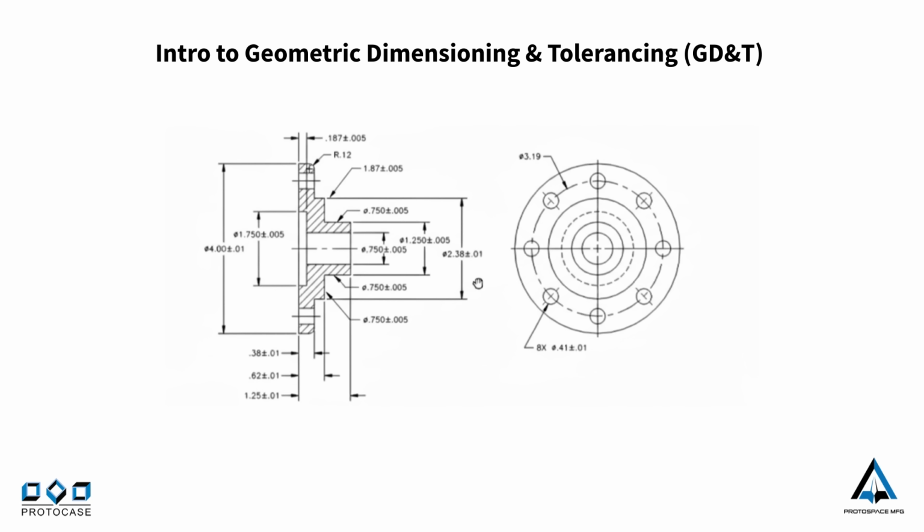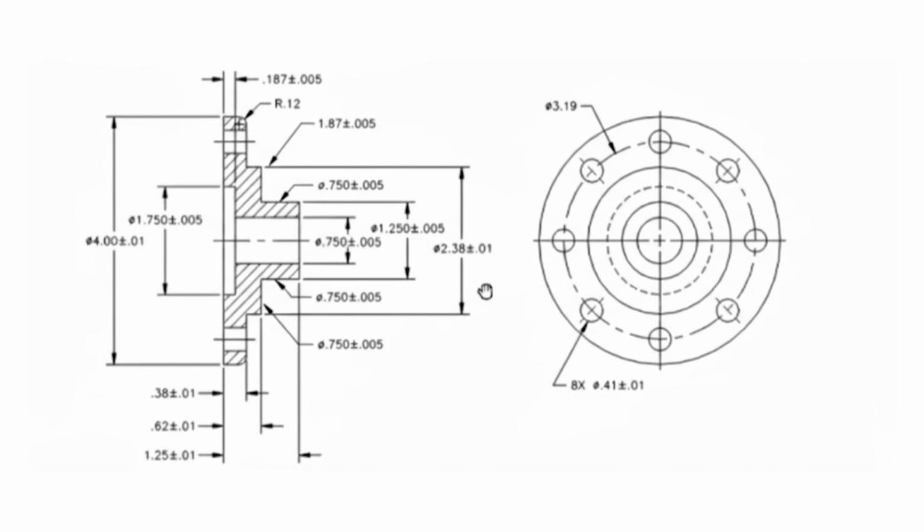So let's start off by looking at this particular drawing. This is a fully defined drawing. There's nothing preventing us from manufacturing this part, but it may be missing some critical information that identifies the truly important features. There is no GD&T on the above drawing. Can the OD be out of round? Does it need to be concentric? How non-flat can the front face be?